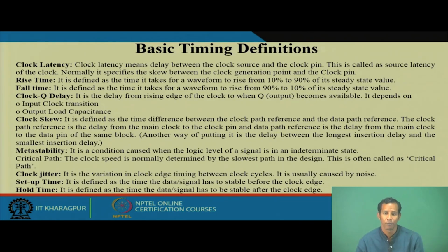And what I said is that whenever you design one circuit, that means an IC, your core has the clock pin. Now, the full chip will be covered by input output pads, where these pads will be connected to the real world. There is a gap between the pad cell and the input pin of the core.